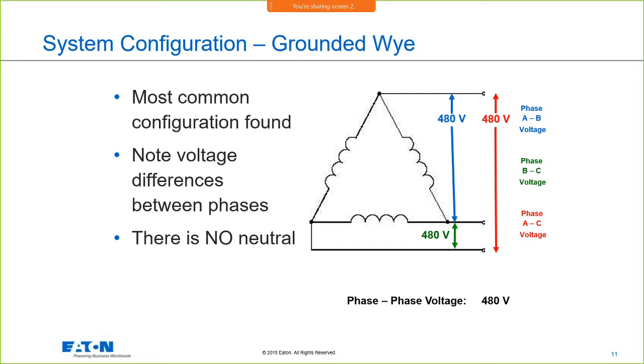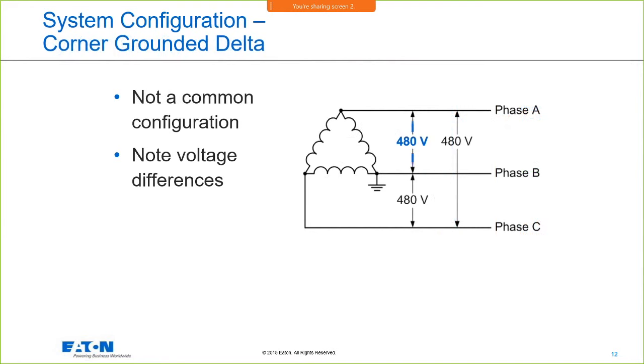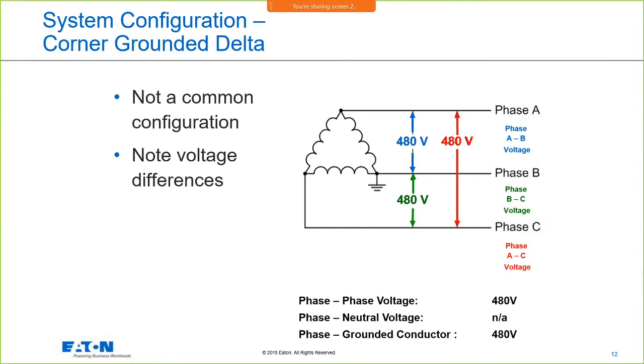And most of our breakers that you would see in this application are 600 volts anyway, so everything's covered. And there's your corner grounded delta. These became very popular back in the day when we were moving from ungrounded to grounded systems, because we were having all kinds of issues with overvoltages due to ungrounded systems, and they decided to ground them because it's like the boat floating in the water. If you don't have the anchor down, you'll float wherever you want to go from a voltage